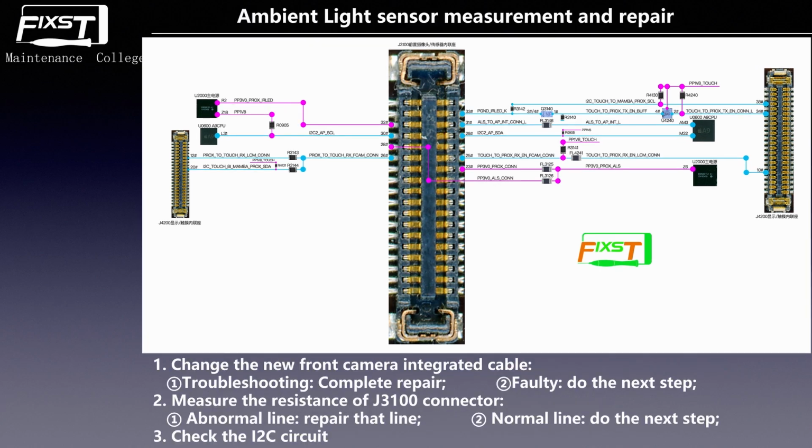Before, we talked about how the display circuit needs two conditions to work normally: one is power, second is signal, right? And it has two powers, right? One power is from the PMU and the second power is from the U4000 display touch power IC.